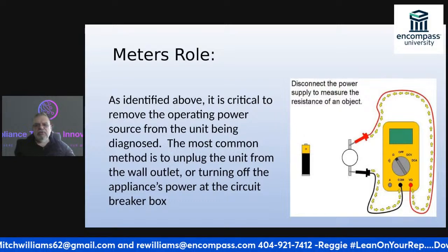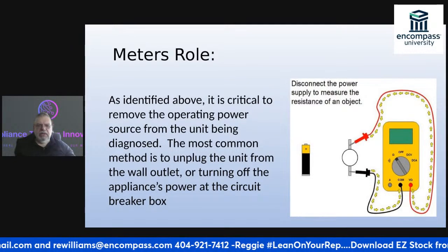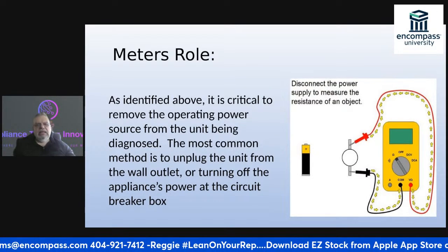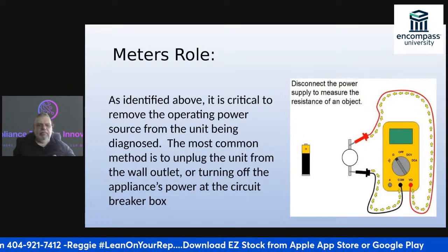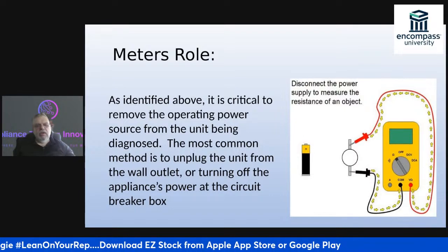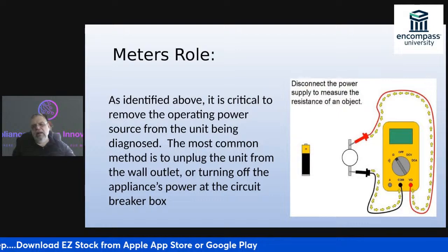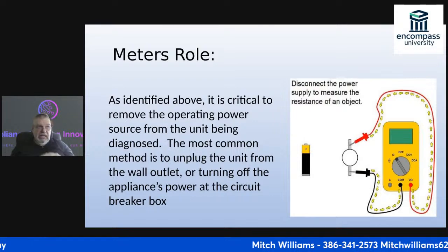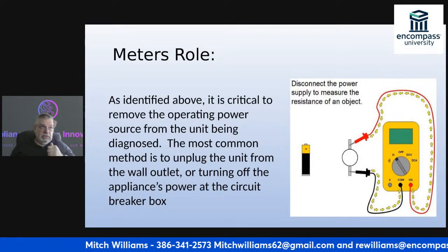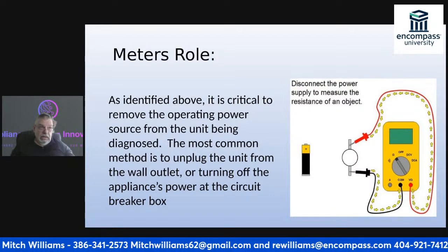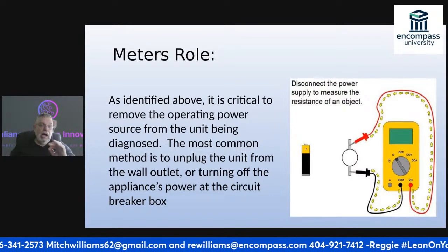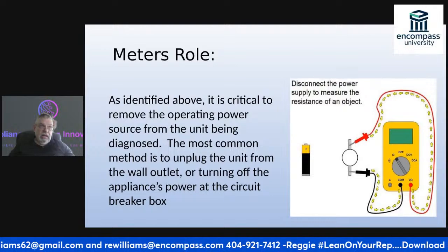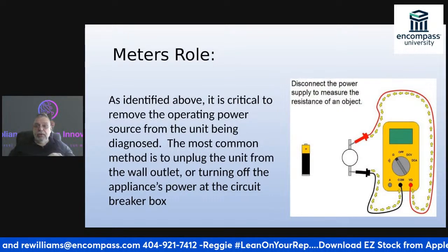The meter's role is critical to remove the operating power source from the unit before being diagnosed. The first thing that I always tell everybody is if I'm going to measure something that is not current related, whether that be amps or volts, I do not want the unit plugged in.